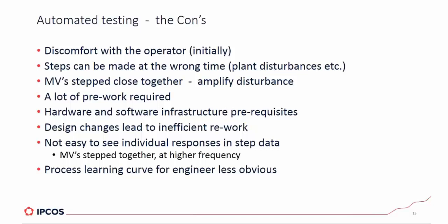Of course, we could go back to our setup and change certain limits on the plant, change the frequency at which testing takes place. But of course, the fact that the step test application has to introduce some kind of randomness into the testing pattern always makes the possibility of this happening again just more likely than a manual step test.